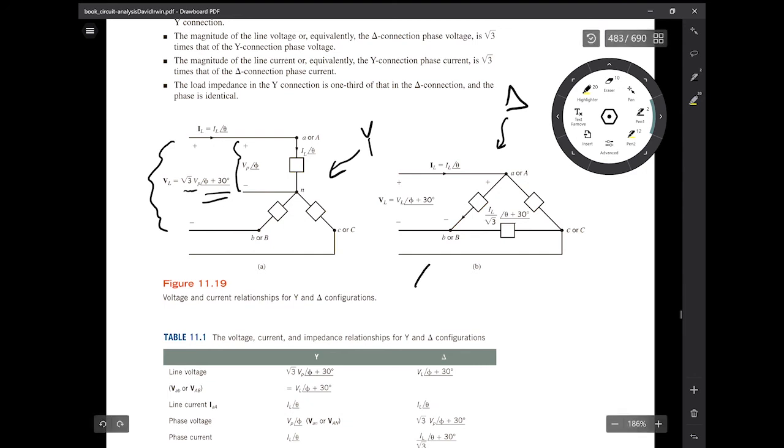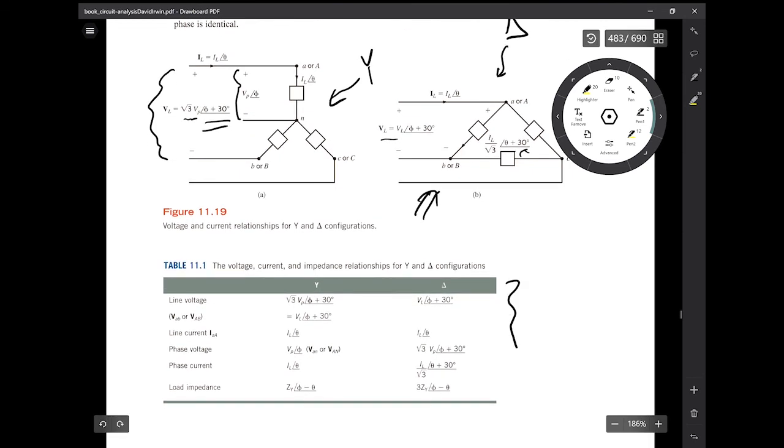And the same way here, this is the summary for the delta-connected load. Assuming that the line-to-line voltage is at phi, with the Y-connected equivalent as the reference, it's phi for the Y equivalent voltage plus 30 degrees, and then this shows the angle of the current. It's also going to be plus 30 degrees, and then the other two phases are going to be minus 120, plus 120, and so on. So this table summarizes all those relationships.